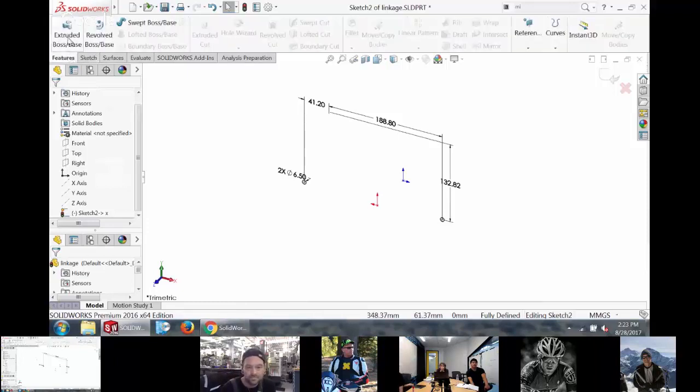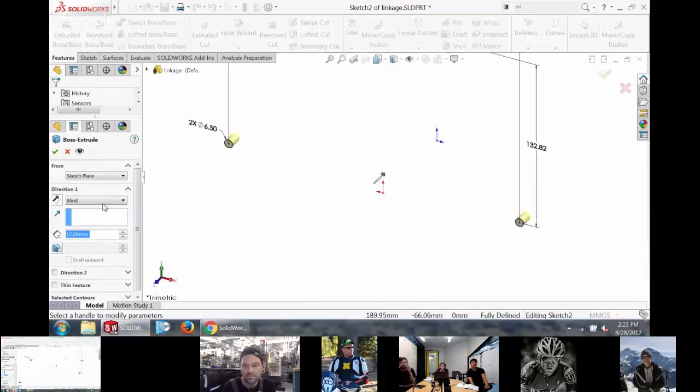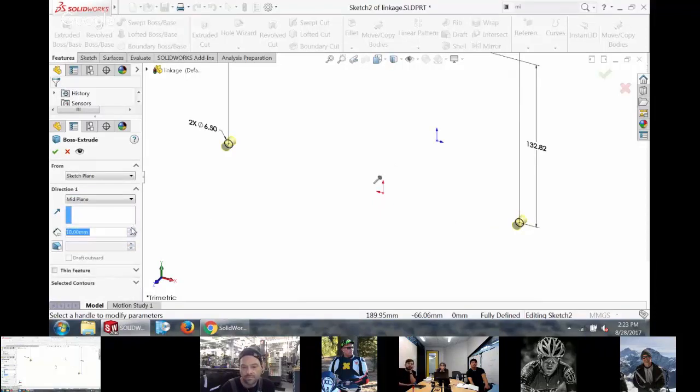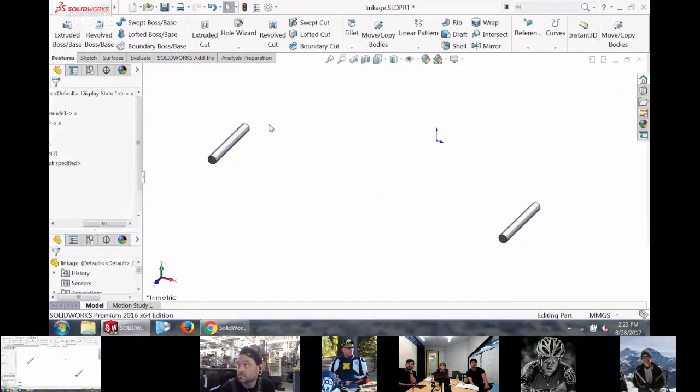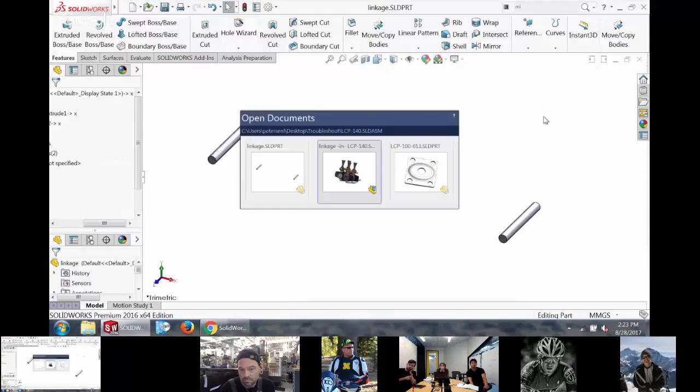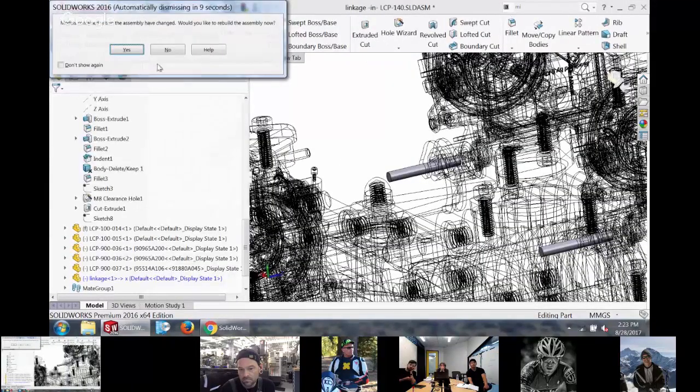But it's one of those things, you know, when do you actually make that break of not using external references or using external references? I try to not have them in there as much as possible. As I had stated already, they are a really powerful tool when you're in the research and development side of your design. But as you start locking it down, it's a good idea to start removing those.